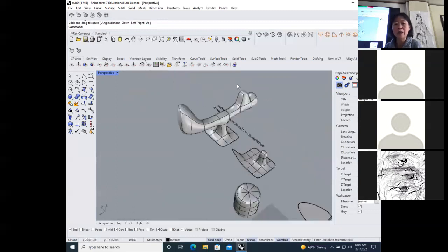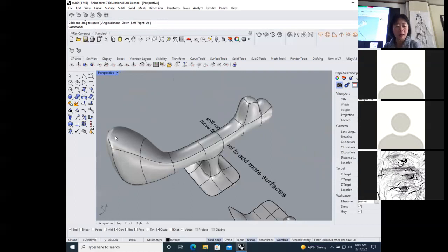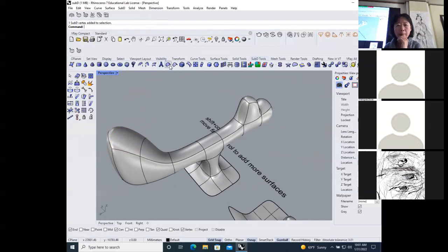So let me try with this. I could fail. I plan to select this surface, and maybe I need to first select the bridge tool. Where is the bridge? Bridge looks like a bridge. Yes, this. Select the first set of edges or faces. Select this one and press enter when done. Select second set. So keep reading. Press enter when done.